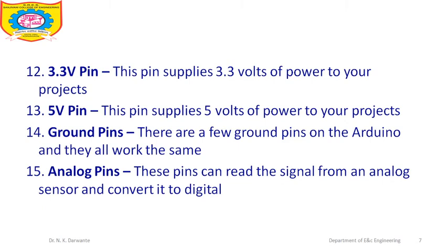The 12th part is the 3.3 volt pin. If in your project you need a 3.3 volt power supply, then you don't have to use a different circuit; it is readily available with the help of this Arduino board. Wherever you need 3.3 volts, you can get it from the Arduino board. For that purpose the pin is available.